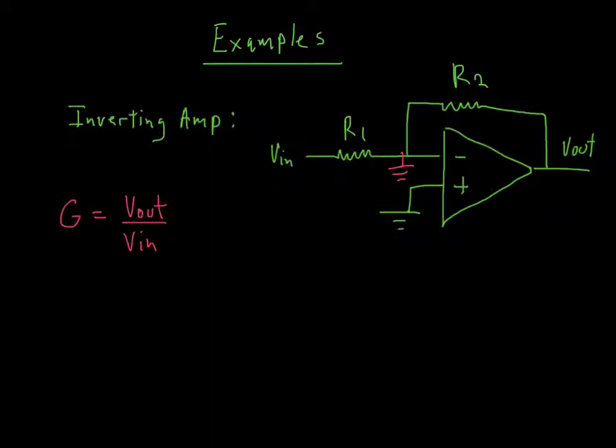Well, let's calculate currents and use V in and V out and the resistors to figure out what's going on here. If this really is in fact ground over here, let's assume a current I is going that way to ground, all right? Oh, but check it out. There's also a V out here and the ground here, so there must be a current going this way. All right, and here's the weird thing. Those currents are the same because there's no junction here.